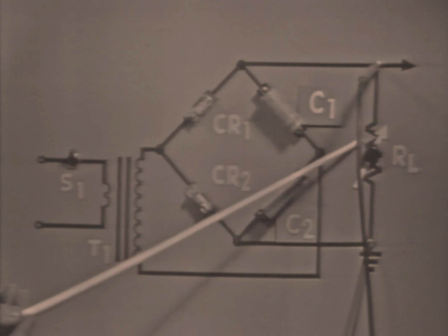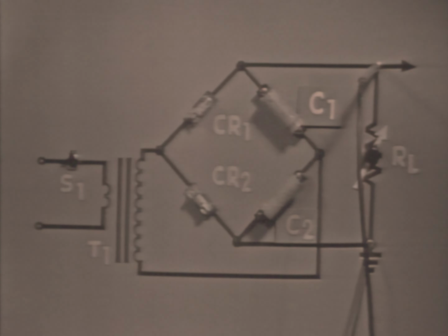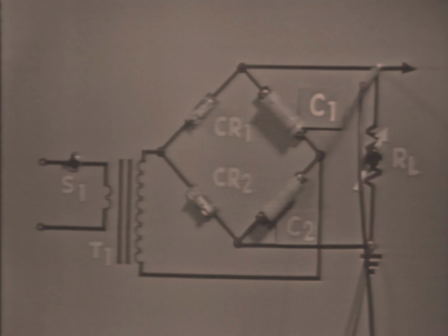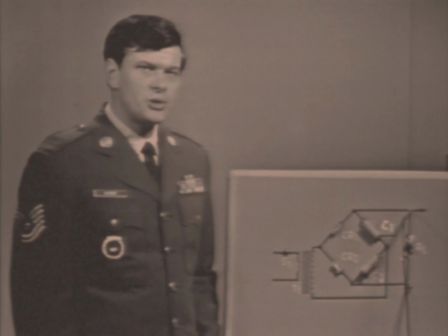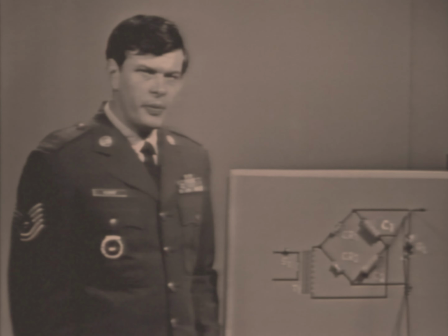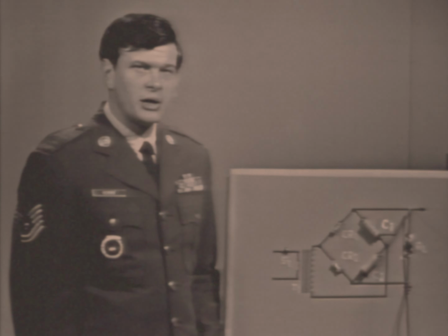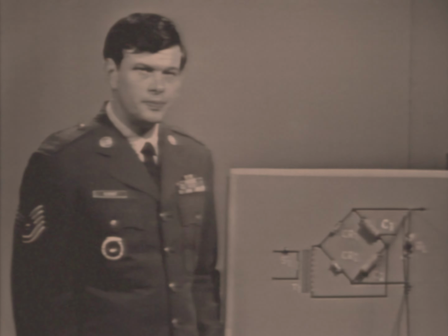If the load on the circuit increases, resistance decreases, and this decrease in resistance shortens the time for one time constant. This then allows the capacitors, that's C1 and C2 in this circuit, to discharge a greater amount between cycles of the input. So, average output voltage decreases. By isolating a portion of the circuit, namely C1, C2, and the load, we've been able to analyze several important facts pertaining to voltage doubler operation.